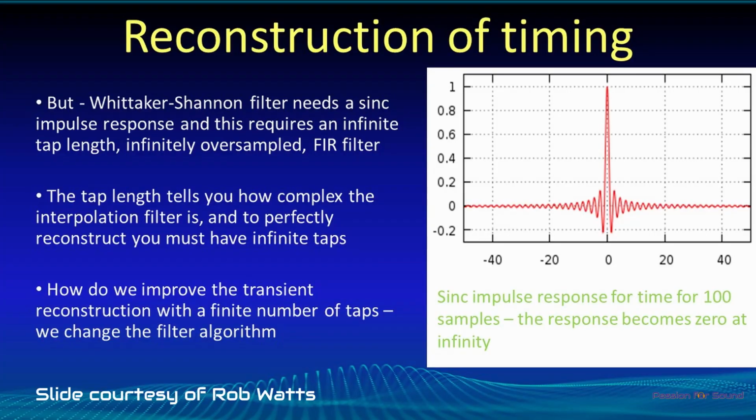The only way of eliminating that issue is to use a Sinc function. So I thought, okay, we've got 16-bit digital data. How can we reconstruct this so that we get the waveform to 16-bit accurate? And when you do the sums on the back of an envelope, you come up with something like more than 500,000 taps, 750,000 taps.